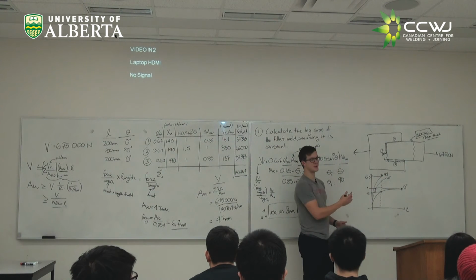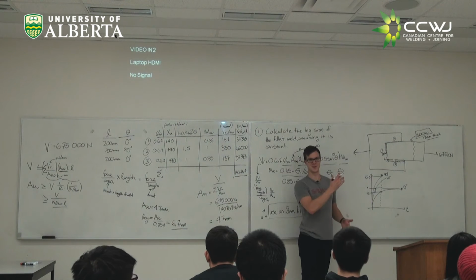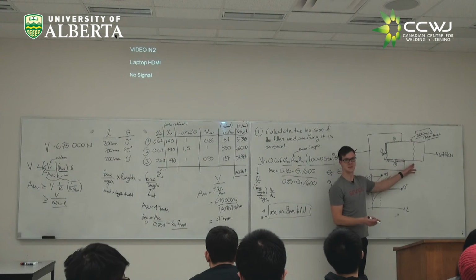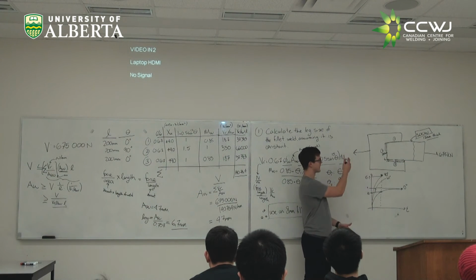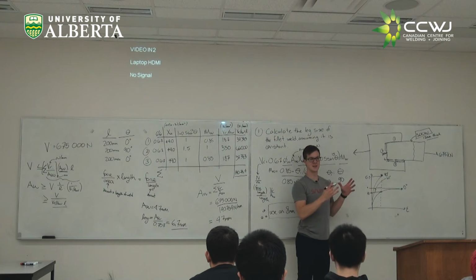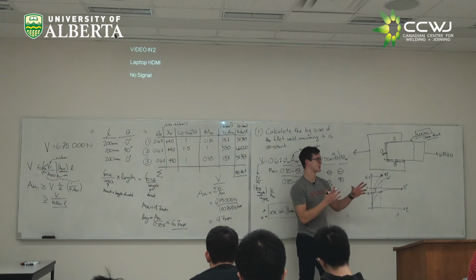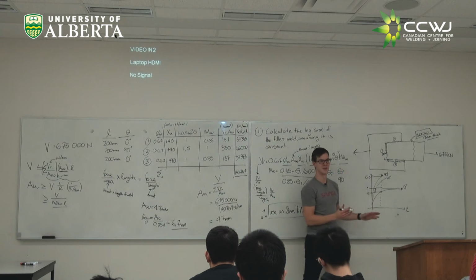So you mean strain is the thing you're really looking at? Looking at it like this, we also don't want to ever reach a point where the stress in our structure has failed, right? When we talked about this, if you look at it where you've got a lot of different welds at different orientations, the strain is what has to be the same in those welds if we assume this is fairly rigid.